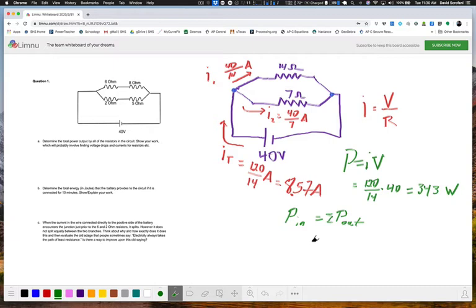Okay, now if you wanted to go through and actually check to see if that's valid, you certainly could do that. And if you did, you probably would want to use a different formula to calculate the power dissipated in each resistor, because right now I don't technically know the voltage drops across the different resistors. I mean, coming back to the original diagram, I know that the voltage drop across those two is 40, and similarly for the two in the bottom branch, but I don't know the individual voltage drops across each one. I realize they have to sum to 40, sorry, I misspoke, to 40, but they're not equal. In other words, it's not like you have a 20 volt drop here and a 20 volt drop here, because those are different resistances, so you would expect to have the larger voltage drop across the larger resistor.